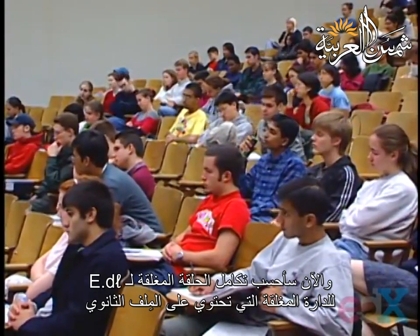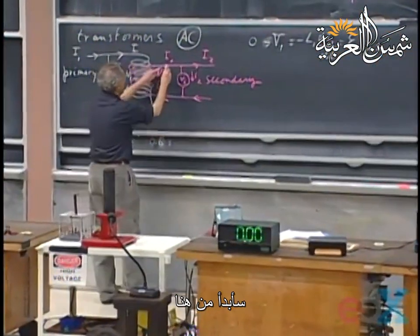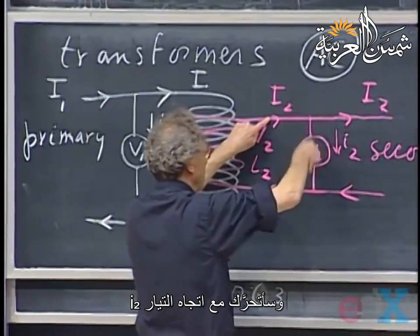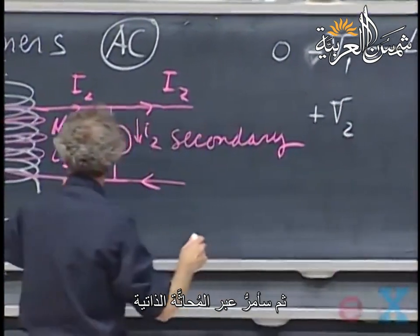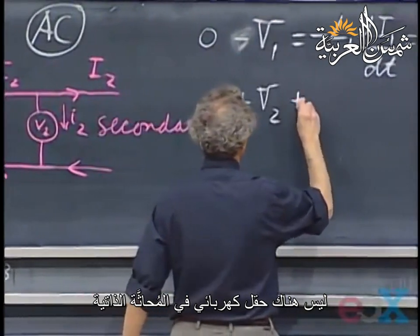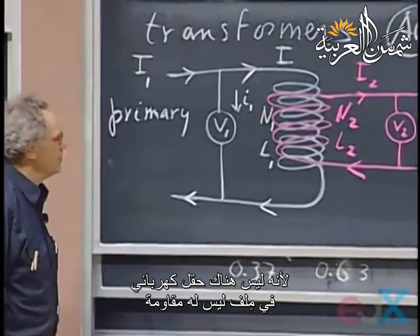I know that this is the electric field induced inside one. And now I do the same on the secondary side. I start here. The current I2 is in the same direction as the direction that I move, so I have plus V2. Then I go through the self-inductor. There's no electric field in the self-inductor, because there's no electric field in a wire that has no resistance.